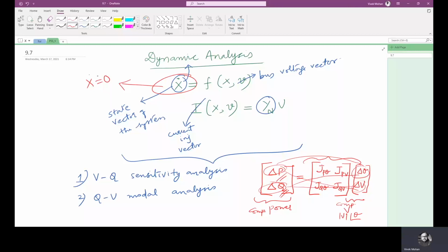Stability is determined by computing the PV and QV curves at selected load buses under consideration. We have already seen the importance of PV and QV curves. In the PV curve, we have seen the collapse point. The loadability of the system depends on the PV curve of the system. Then in the QV curve, we analyzed the slope of the curve to determine the stability at different operating points.